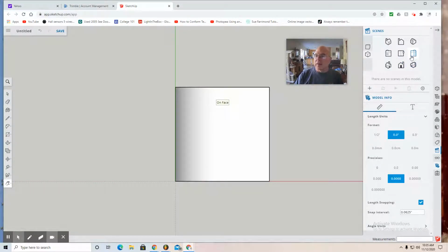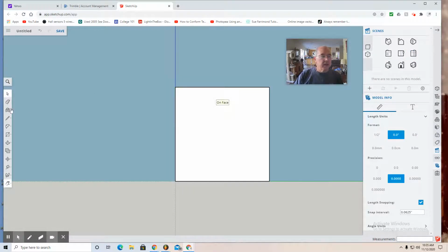I'd say look at it from right view here, and use your line tool to measure from the bottom right corner, click, and go up half an inch. You should see midpoint right there. See where the balloon is? That's 0.75 from the bottom. And then click, and click again, drag it across. You're now creating just guidelines where you're going to center your circle. So I'm going to click, drag it across the x-axis until I find midpoint or 0.75. Then I click once, click twice. And now this point right in the middle will be the center.